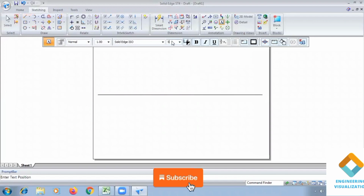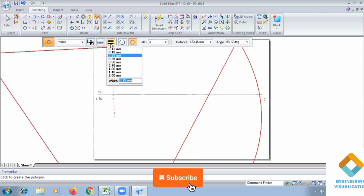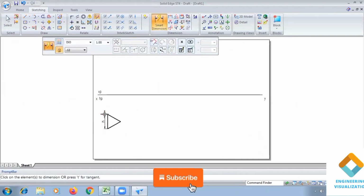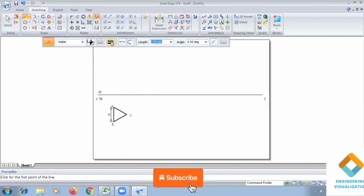So first I'll draw the XY line, writing HP and VP since it is lying in the first quadrant. Go to polygon by center and select the number of sides as 3, and resting with respect to edge. Now go to smart dimension, select the vertical edge here, and give 25. I'm showing this problem with a 25 dimension. The same thing you can do in the exam for 50. Based on the question given, you need to do it. For showing purposes I'm doing it for 25, but the procedure will be the same. So draw the projection lines to complete the top view.